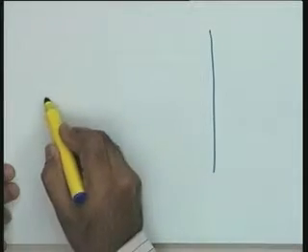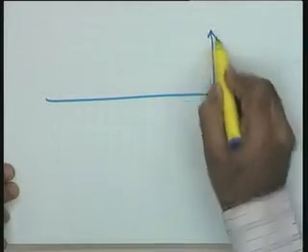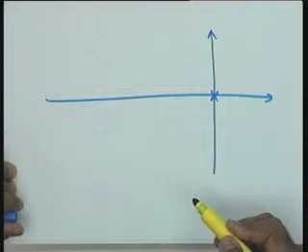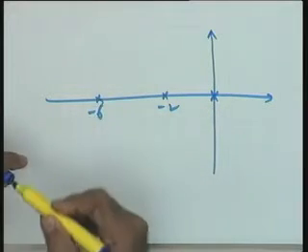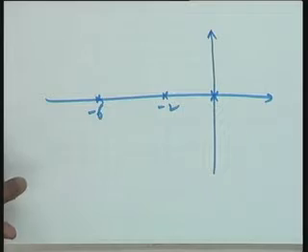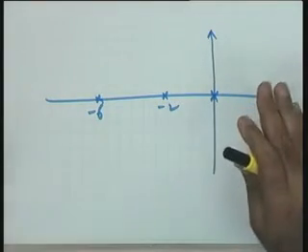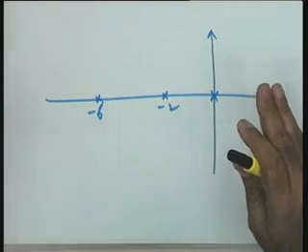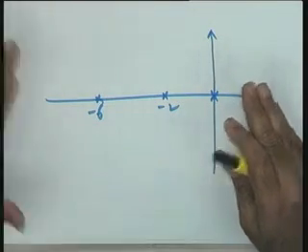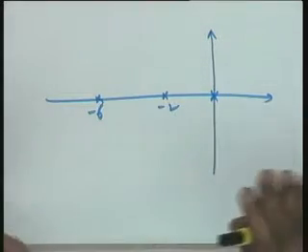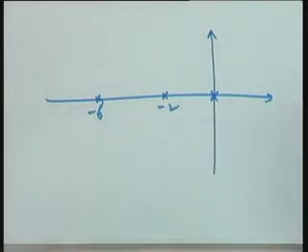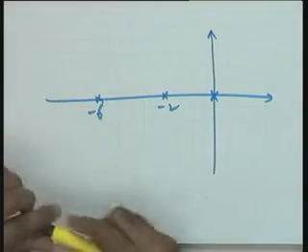But let us see the root locus plot for this system with K equal to 60. You see that this is one point, K equal to 0, at -2 and -6. Let us make a rough root locus sketch. I will not give you those rules now. What is the centroid, what are the angles, what is the breakaway point, all these things I am sure you will be able to calculate. I give you a rough root locus sketch and go ahead with my design comments.